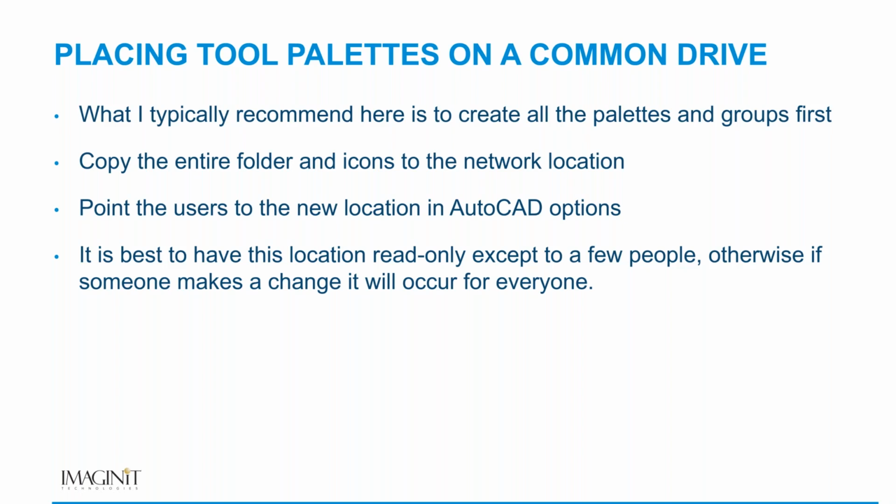Can tool palettes be run from off SharePoint for multiple users? Sean, the short answer is yes. Long answer is yes, with some caveats. SharePoint is not officially supported by Autodesk. You may have some errant behaviors. And there's another thing that is here, which I typically recommend: create all the palettes and groups first, copy the entire folder and icons to your network location, point the users to the new location in AutoCAD options, and it's best to have this location read-only except for a few people. Otherwise, if someone makes a change in their palette, it will affect everyone.